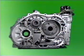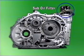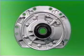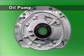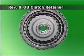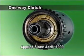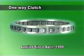Filtering capacity has been further improved by adopting extra sub-oil filter along with main oil filter. Engine oil filter shouldn't be used for the automatic transaxle oil filter. Filters are usually changed when automatic transaxle fluid is changed. Oil pump should be replaced by the unit of assembly. Retainer for both reverse clutch and overdrive clutch have a common retainer. One-way clutch is applied to fix the low and reverse brake annulus gear.